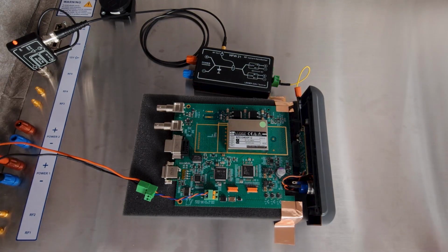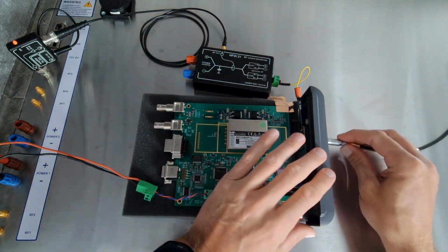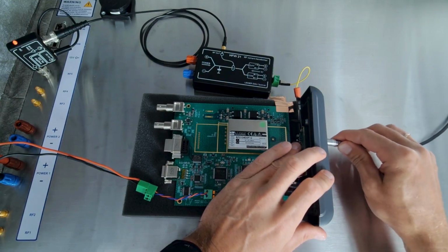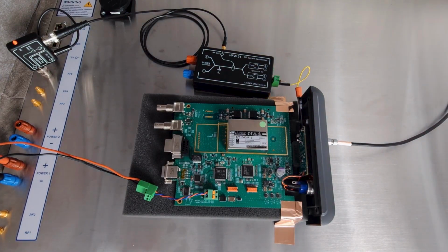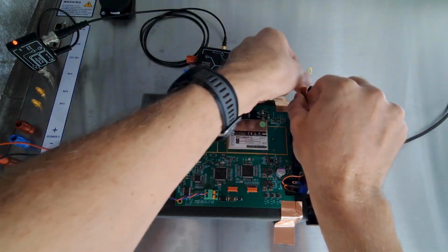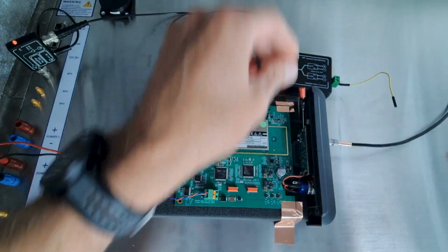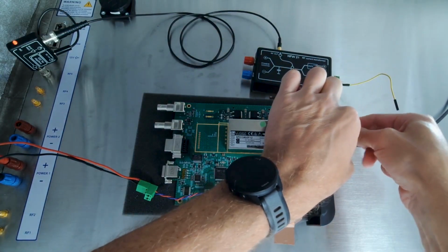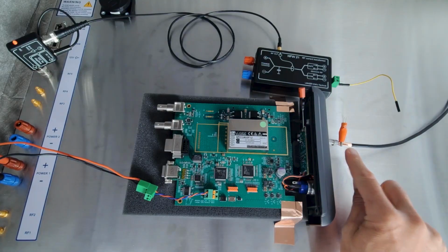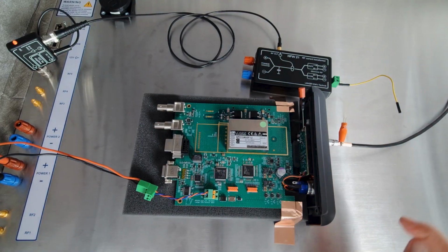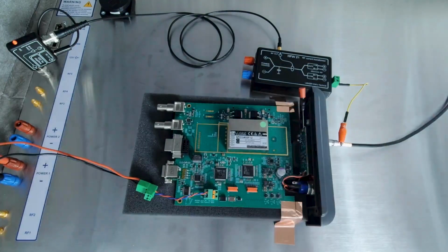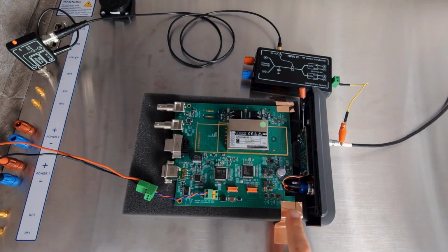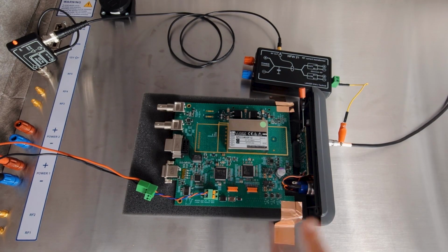You also have the option, if you have, for example, a shielded cable like this one, which is connected to the device under test, to connect the RF current transformer directly to the shielding. Here I removed the isolation of the shielding, and then you connect the current transformer to the shielding here. Because of that, this ground of the main PCB is connected to the reference plane,